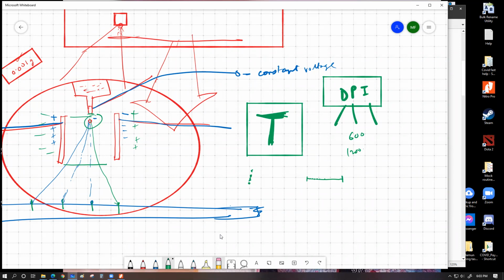So your printing time, the amount of time it takes for one page to go in and come out on the other side being printed, is going to be more. If you try to print a picture at a higher DPI, you're going to get a much better resolution and a good looking picture, but it's definitely going to cost you a bit more time. But if you have a lower DPI, it's going to print much faster, because you are going to have big size drops, so you're going to require fewer drops. You do understand that in this case, you simply have double the number of dots. So you have to control the motion of 1200 dots over here. In this case, you have to control only 600 dots over here.